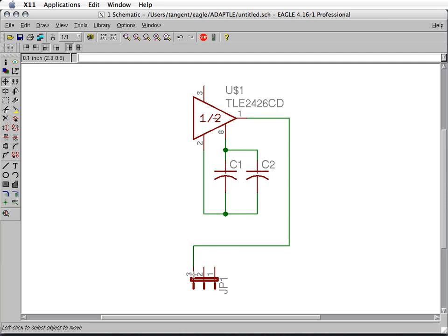But I've got a new problem, which is that my pins are now numbered backwards. So I'm going to click on it again. I'm still in the move tool, so I can click on it again, and now if I hit the middle mouse button, I've flipped it. Okay, and so middle mouse button will mirror it back and forth. Right mouse button rotates it, and then as I drag my mouse around, I can get it to come around into the way I want. So between those three mouse buttons and moving it around, you can quickly rotate and flip and move a part until it's the way you want. So now I've got my pins in the proper order, and the pins are upward the way I want. So very quickly I can fix its default arrangement until I get it to be the way I want it to be.